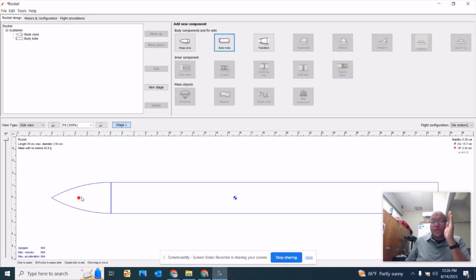Now, one of the things that's really important is that you want the center of gravity for your rocket when it's standing up to be straight down the middle, because if the center of gravity is either to the left or to the right, then your rocket, once it launches, is going to veer either to the left or to the right, based upon your center of gravity. Now, this horizontal center of gravity, you want this to be somewhere near the leading edge of your main wing, okay?